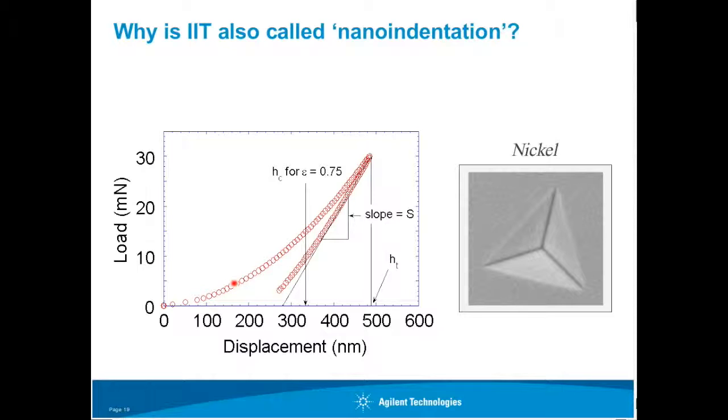But what you really have to pay attention to is that for many materials, especially metals, the hardness that you measure depends on the strain that you're imposing in the material by virtue of the test. So, for example, because those materials increase their yield stress in response to strain, okay?